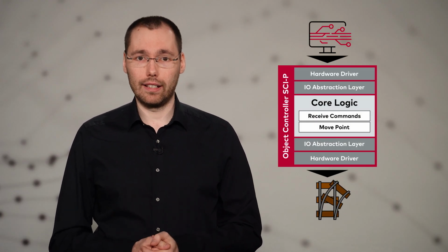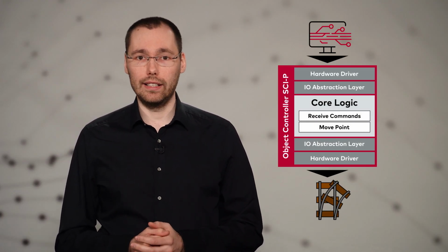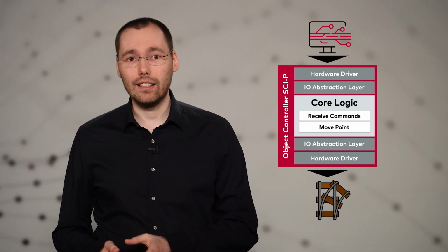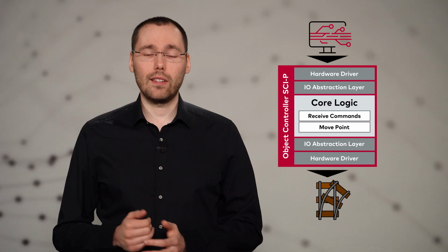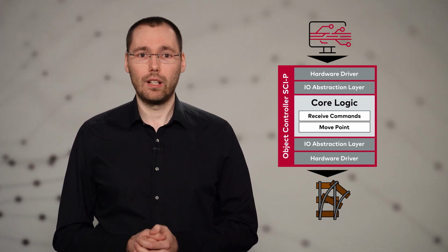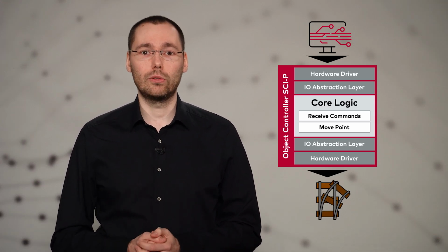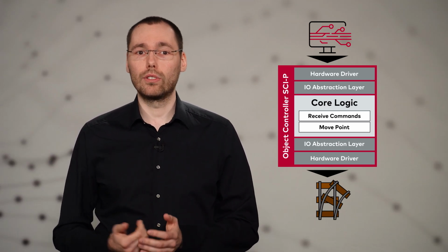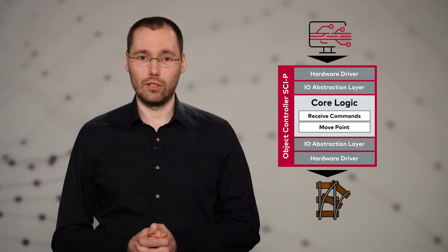When we want to reuse test cases across different environments like SIL and HIL, we should introduce an I/O abstraction layer in the software under test and in the test tool. Within the software under test, this abstraction is a software layer that provides a consistent interface between the application logic and the underlying hardware. It abstracts away the hardware-specific details, allowing the same application code to run on different platforms, for example simulations, emulators or real hardware, without modification.